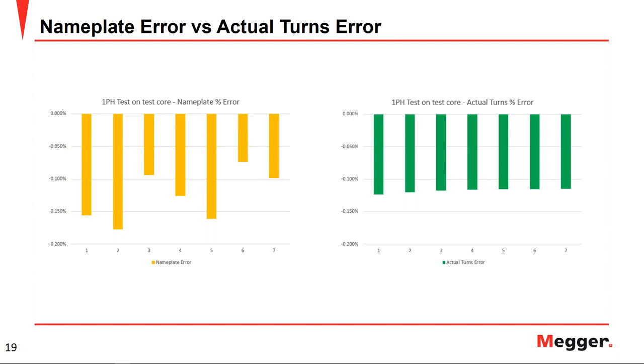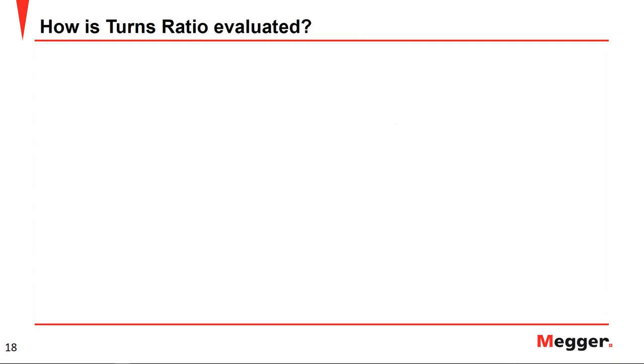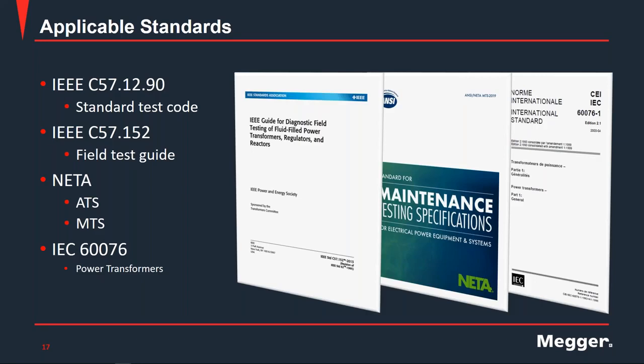And the excitation test is a voltage dependent test. If I try to run the test at 500 volt, 1000 volt, and 5000 volt, I will get different excitation current measurements. Now the question is asking about the relation between rated voltage and excitation voltage. You don't want to exceed the rated voltage when you're performing the excitation test, and you want to apply as high a voltage as possible, not to exceed the rated line to neutral voltage. So that's the only criterion I would be mindful of.